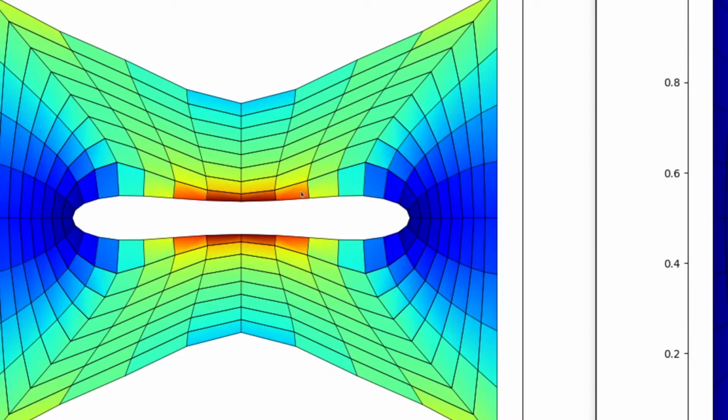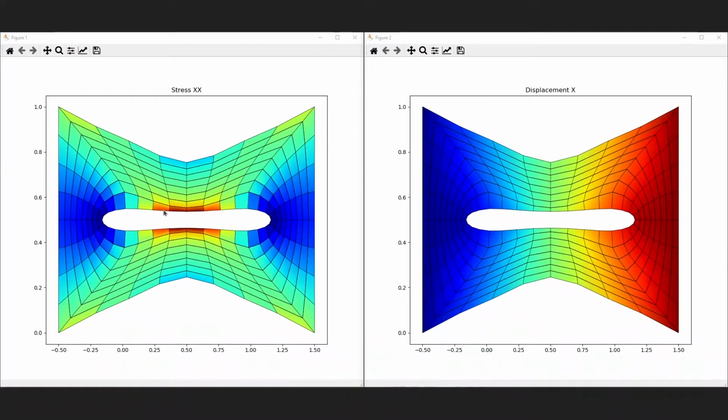Normally, if we were to plot on the Gauss points, let's think about Paraview. I think you've seen Paraview in class. Professor Javili might have shown you Paraview. In Paraview, you can plot the results on the Gauss points instead of the nodes, and you won't have these sharp transitions between the elements. But in this case, since we map the results onto these nodes, we will have this little transition, and this is why the plot is not smooth.